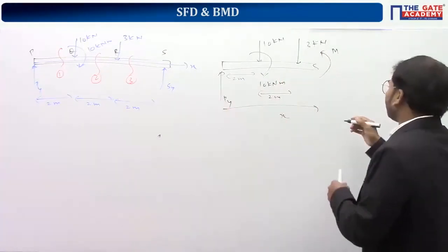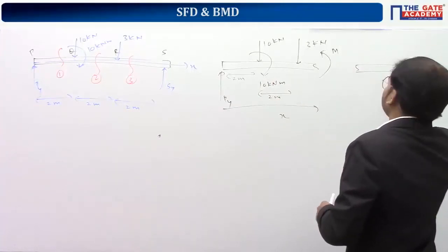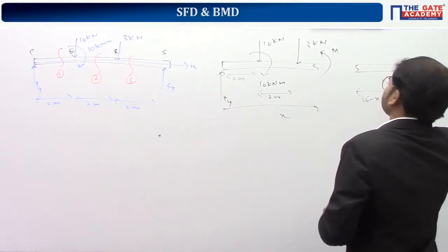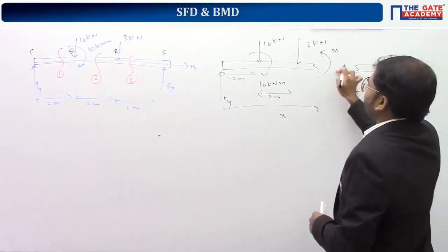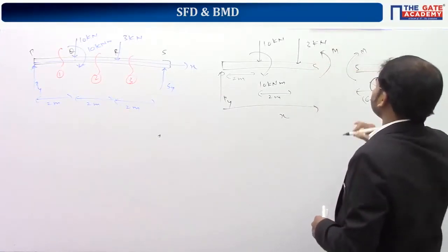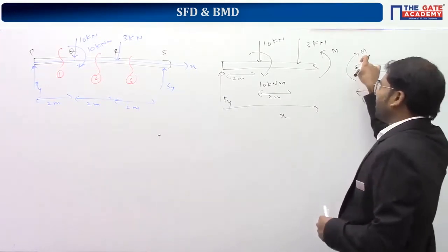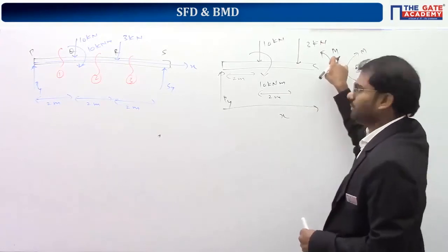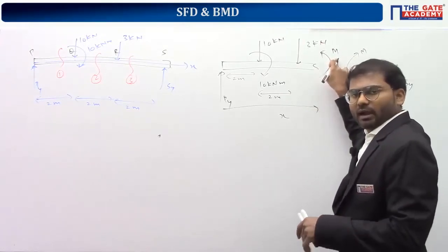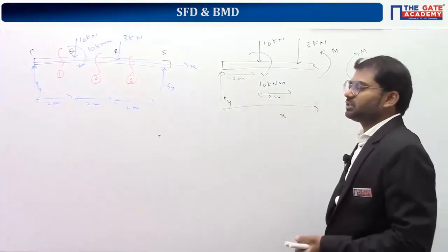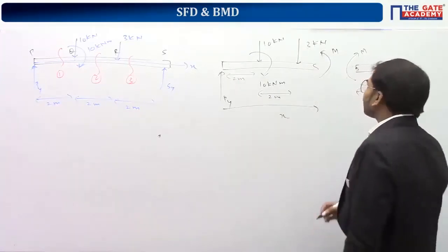Instead, if you take the right part of the cut, this becomes a total of 6 minus x. Here there's a force of Sy. Here it was anti-clockwise, but it should be clockwise. So if you take the moment about this point, you'll get this value of M, which is nothing but this M only. And the point x equal to 4 is included in the range.